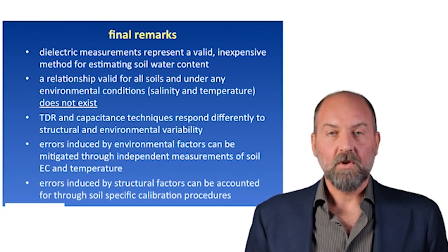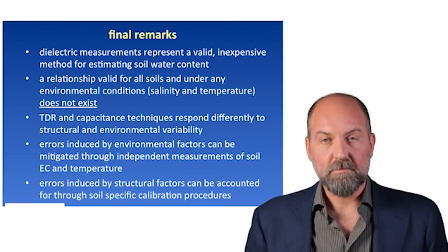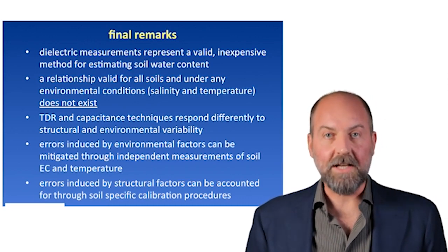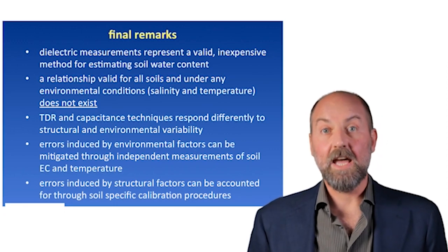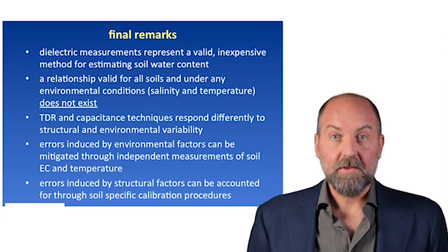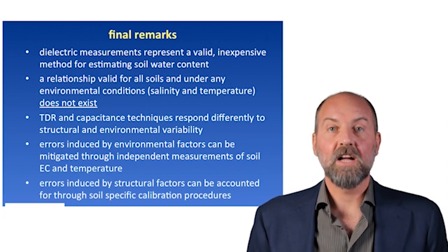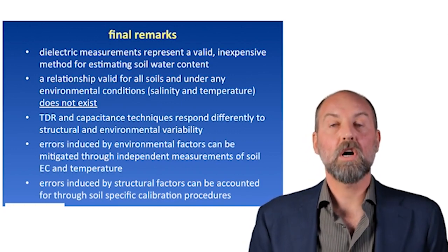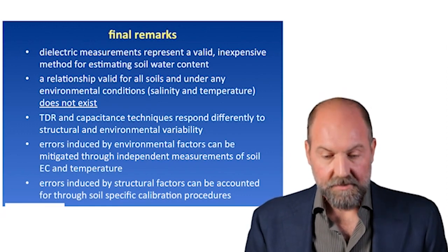And we have also pointed out that a unique relationship, or if you like, a universal relationship between the soil dielectric, whether it is estimated through TDR or capacitance, and water content, a relationship that works well for all soils and under any environmental condition, simply does not exist.